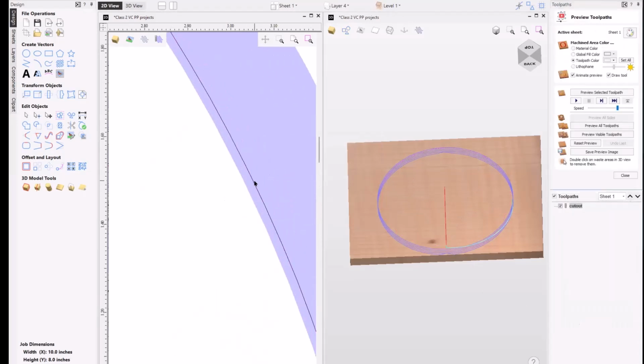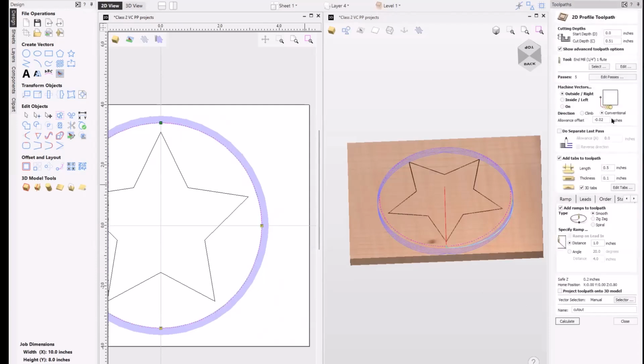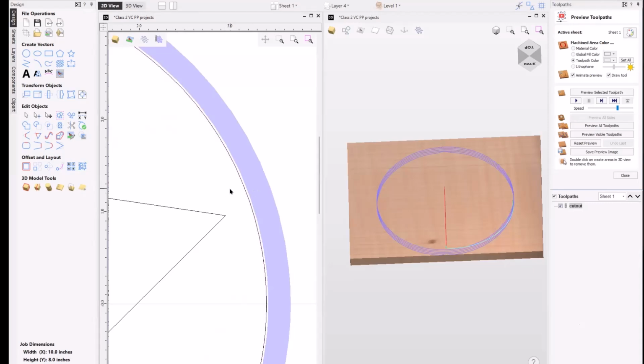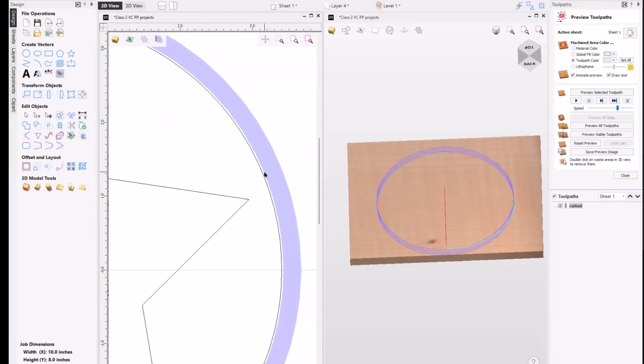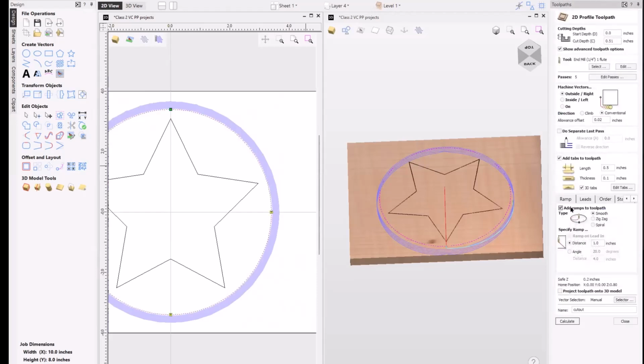And let's zoom in here. Notice now how that toolpath moved in over that line. So now my circle is a little undersized by this amount. So think of this if you're fitting parts together, like puzzle pieces or joints or something like that. This is one way that you could affect that. However, if I wanted it slightly oversized, I could do the opposite. And now it's slightly oversized. It's a handy little setting that when you have the need for it, it's really very powerful.